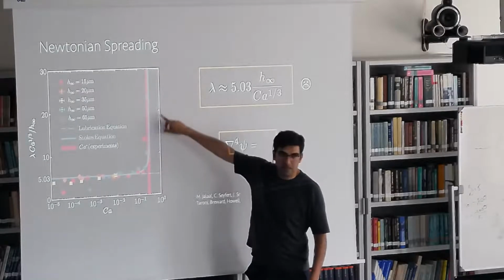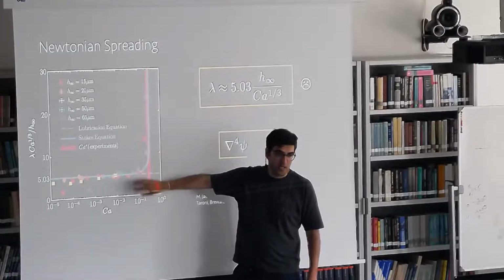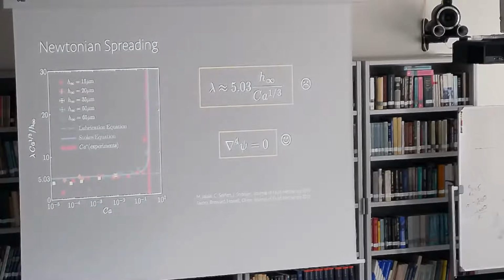So there's this new singularity that we found out. So you can see undulations. This is the amplitude of undulations, in fact, for the Newtonian case. For the viscoplastic case, we have no experimental proof of that. The reason is that you can see mathematically it's not just the wavelength that drops exponentially in the viscoplastic case, but also the amplitude. That means the moment you introduce a little bit of yield stress, these undulations die really quickly. So experimentally they are most likely there, but they're so small that we can't resolve them. Which is unfortunate, but we hope we can do it.